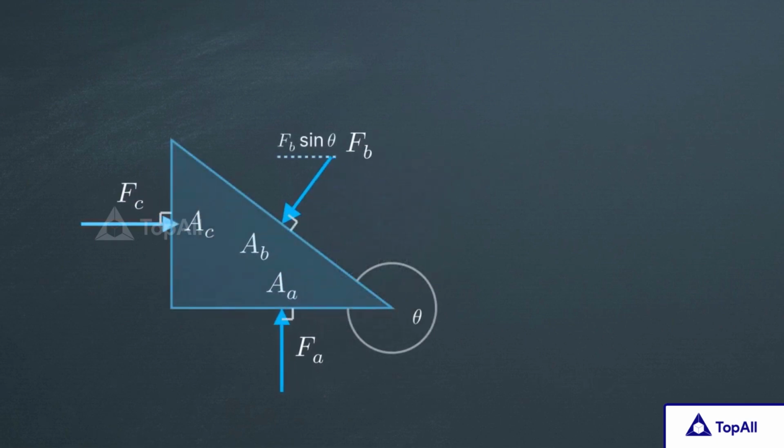Since the prism isn't moving, the horizontal force on the back must be perfectly balanced by the horizontal component of the force on the slanted face. Vertically, the force on the base must match the vertical component of that same slant. This is where the math proves the theory.